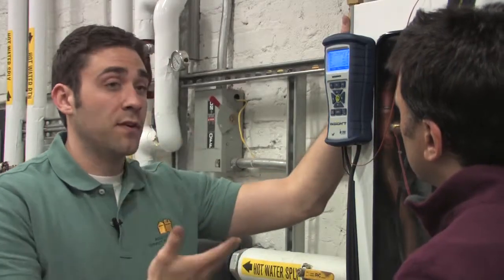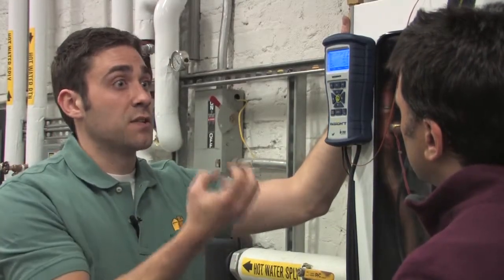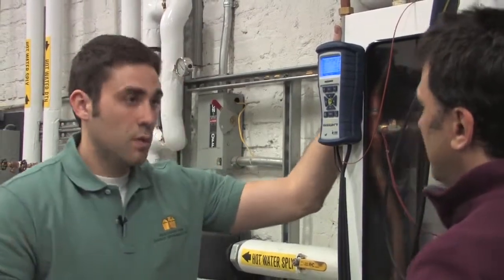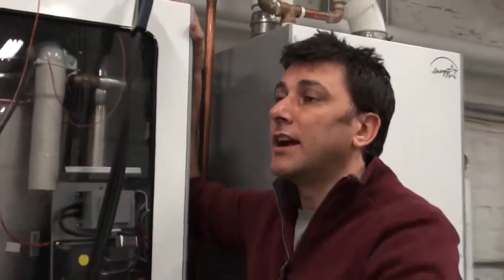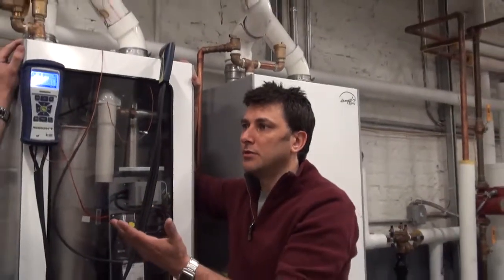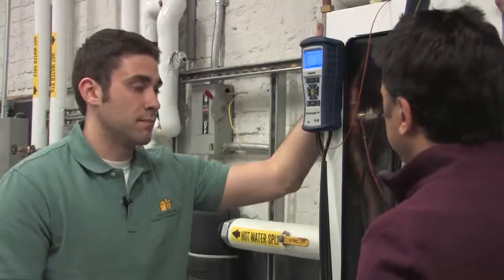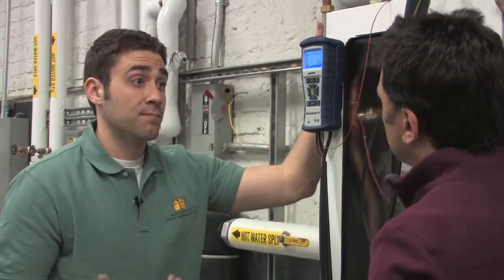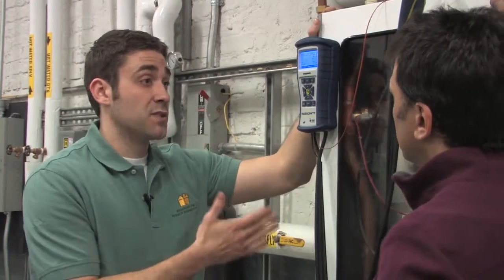Once we get below 135, that's when those flue gases start to condense and start to give up that latent heat. And then we have to deal with it. Which is what we're looking for. That's the efficiency of this. A lot of the heat that was taken up in water vapor is being recaptured. Right. And that's where we get our efficiency spike. Right now, we're running almost 95% efficient. So the efficiency spikes on these are very, very high.